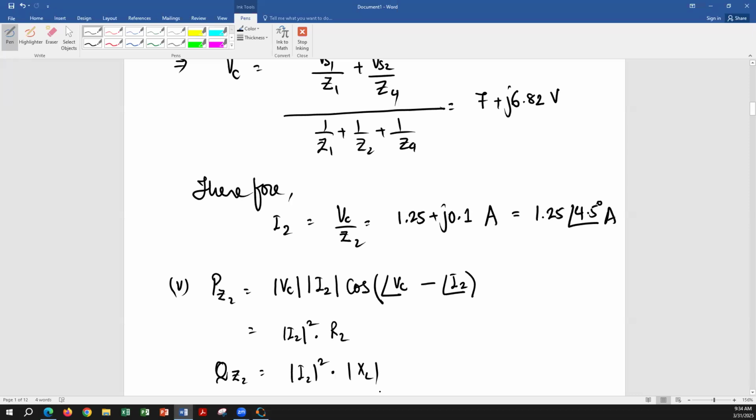So whichever formula you want to use, make sure you use it correctly. As we discussed, do not fall for the voltage, do not use V squared unless you calculate voltage across each component separately, because this VC is the voltage across the total impedance R plus XL.